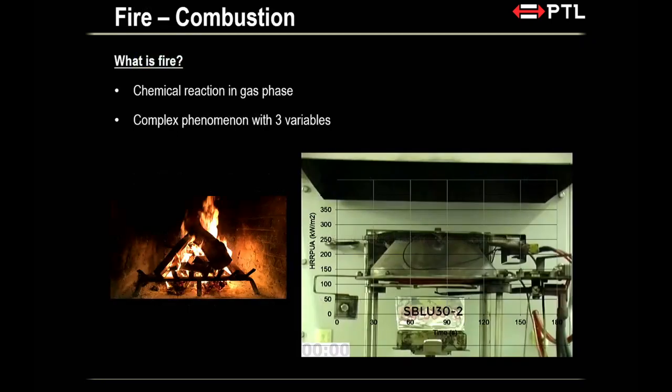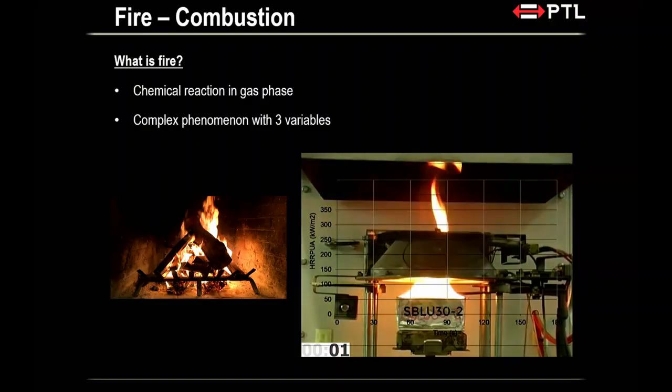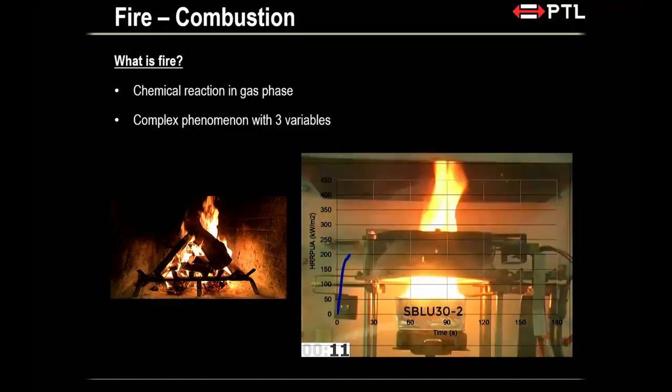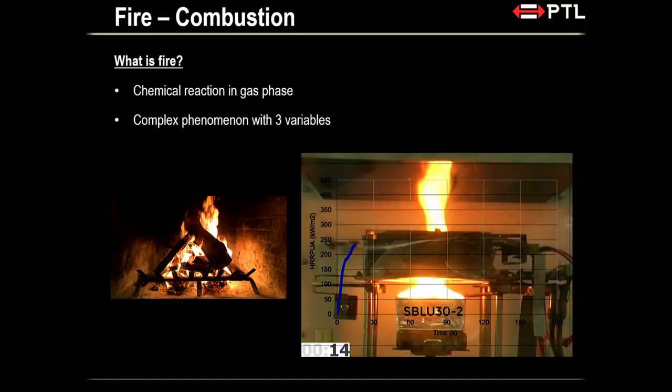All right, so let's move on a little bit. So what is fire, right? Now, you will see that the video will start playing. What we have here is a cone heater, which is our heat source. We have a piece of upholstery furniture, which you're sitting on at the moment, being exposed to the heat source. Now, what you can see on the background is the heat release rate curve.